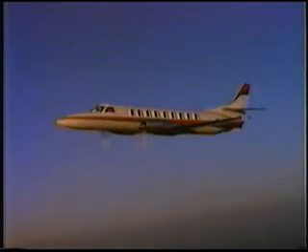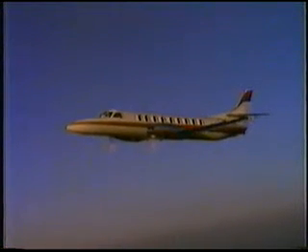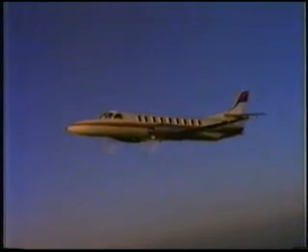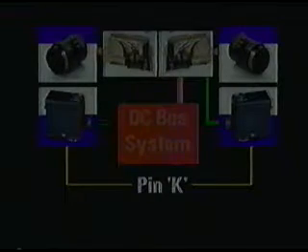During flight, as the electrical loads are increased and decreased, the generator control panels must increase and decrease the output of each generator as well. If at any time either control panel senses that a fault has occurred in its generator wiring, it will immediately open the respective generator relay and disconnect the generator from the bus. The generator control unit for the opposite generator will sense this condition and increase the output of its generator to compensate.